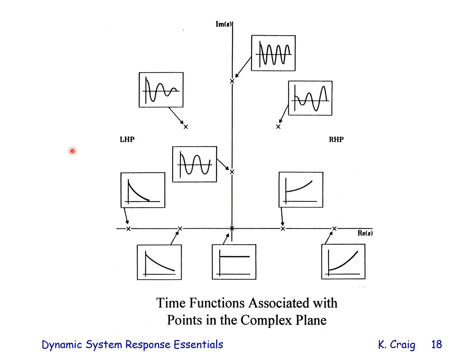This plot is very important for a second order system in order to understand the type of time response, the location of what we call poles, or the roots of the characteristic equation of the second order dynamic system, where they lie in the complex plane, with the real axis being the horizontal, the imaginary axis the vertical. If one of the roots of that quadratic equation, that second order system characteristic equation, which is simply the denominator of the transfer function,